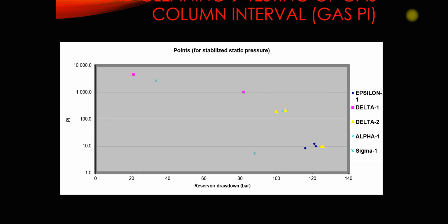So what we know for this well is that we will have a good evaluation for the production index, because we have also reached radial flow stabilization. But it's potentially a bad evaluation for the production index if the well was badly cleaned up. And as a matter of fact, even if it was a modern DST, we have the information that it was not properly cleaned.